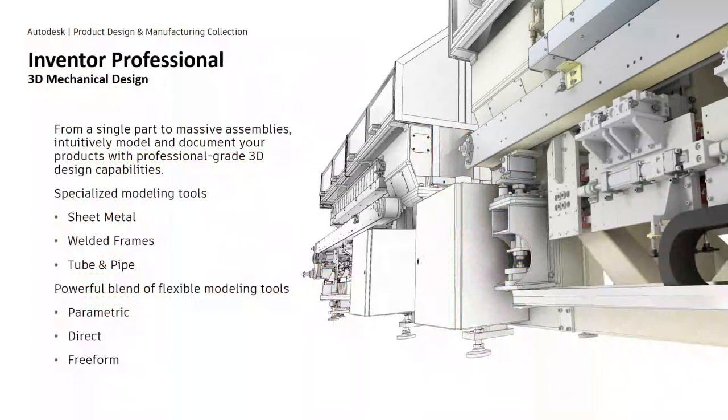What makes Inventor such a great design tool? It enables you as a designer or engineer to focus on your designs, less on how to use each feature and its controls. You're going to find specialized modeling tools to speed up your design, things like sheet metal tools that are available to quickly create the features in your model, and you're able to get an accurate flat pattern to your laser cutter. There's a frame generator. It models in 3D for you as you specify the skeletal structure and a cross-section of choice for each different type of member, whether it be tubing or channel, things like that.